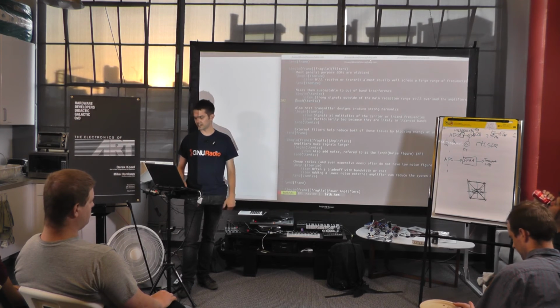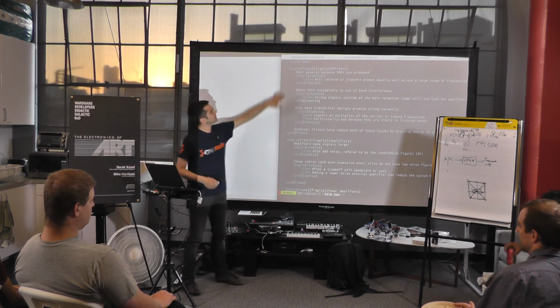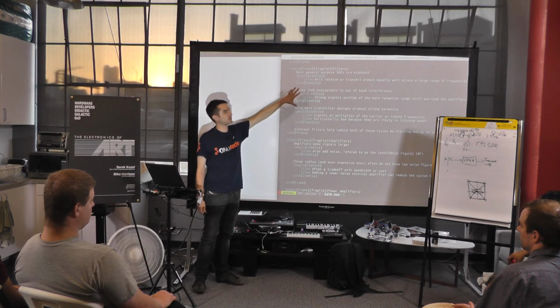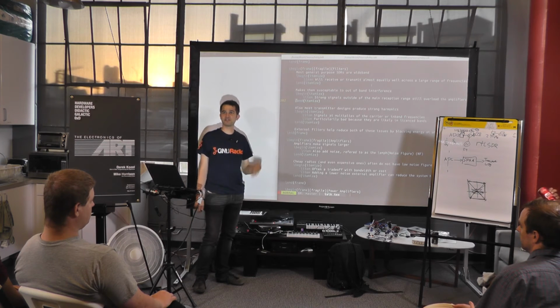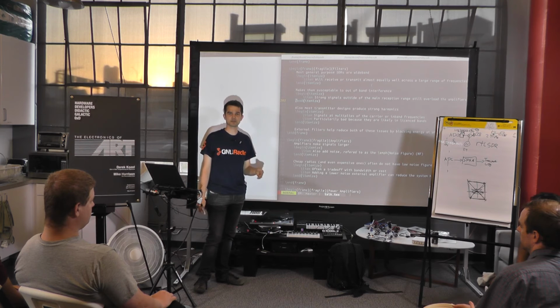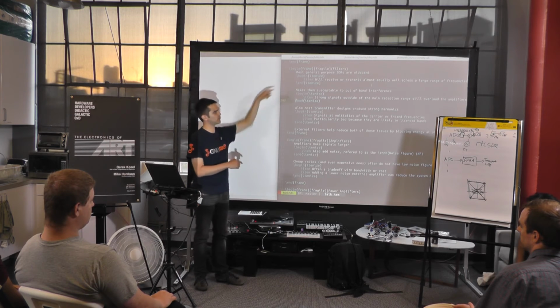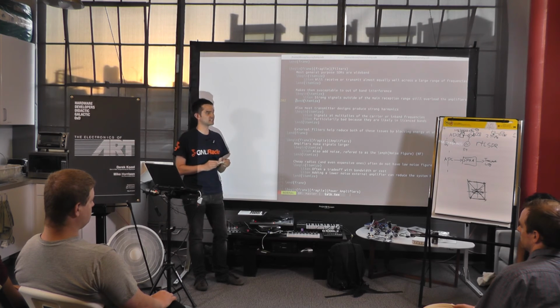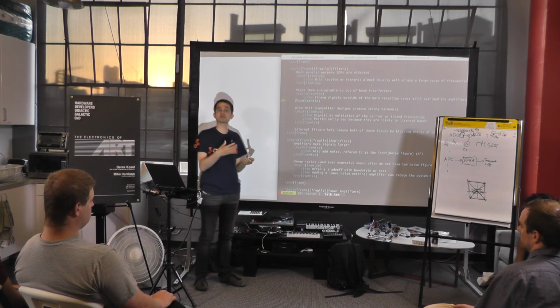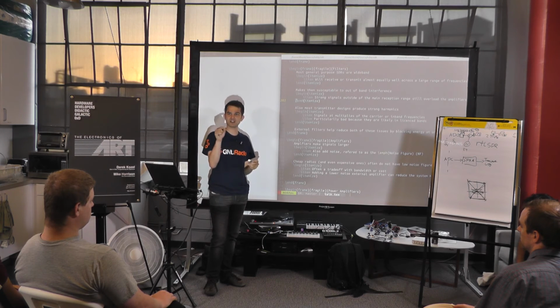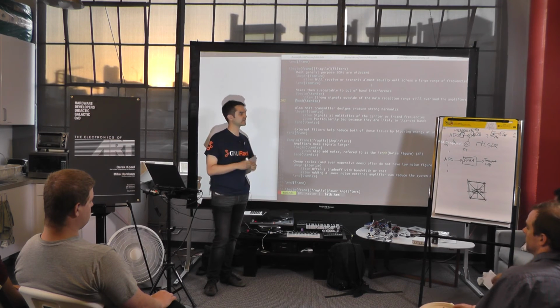Anyways, this isn't very helpful, but one of the things that I wanted to talk about was filters, because if you put a filter out in front of these, you get much better reception. One of the limitations that you end up with in a software-defined radio is that for reception, you have an analog to digital converter that's sampling the waveform of your radio signal very, very quickly. But it only has so much resolution.